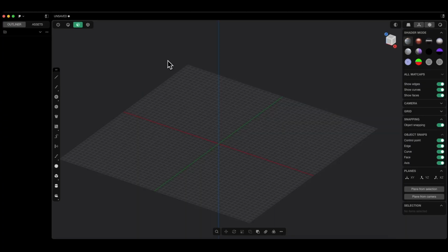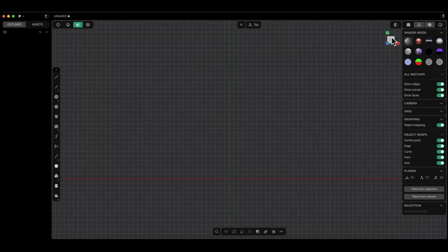Now I will show you another interesting operation. This will be the operation of extruding a profile along a path. First, we will create the profile shape and create a polygon. I will switch to the top view, and when it comes to creating polygons, we have a command here that allows us to create polygons. We select this command and specify the starting point of the polygon.